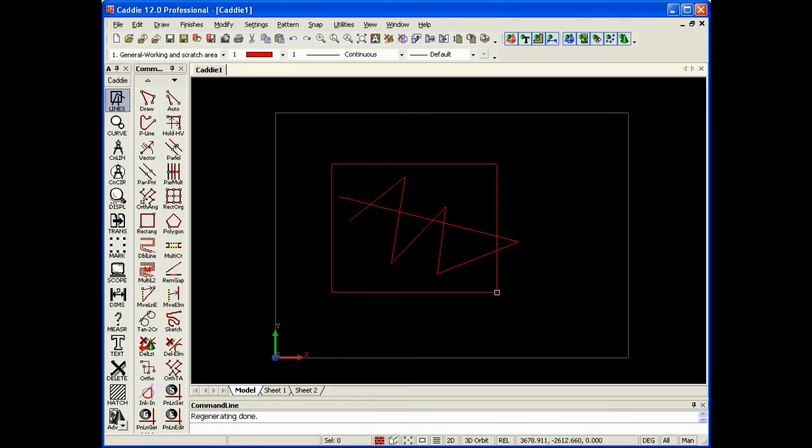We can work in absolute or relative mode, and we can also say how we want the figures to update on the screen here, whether we want coordinates or whether we want distance and angle, for instance. Over at the right we have degrees or radians. We can see whether we're displaying all the layers in the scope, and we can say whether we're selecting the automatic unmark, which is either manual or auto. Okay, that gives us our basic layout.